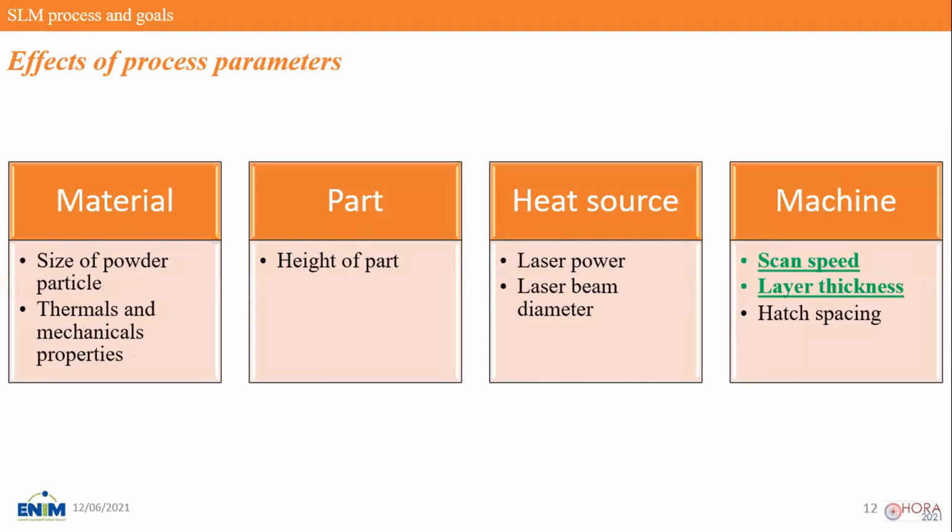Looking at the previous work, it can be seen that there is a lack of simulation on the effect of high layer thickness and scanning speed on melt pool dimension and on final part quality. Therefore, a better understanding of this process by analyzing this effect is needed.